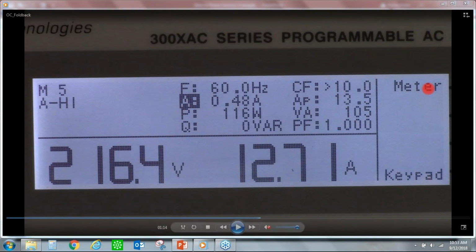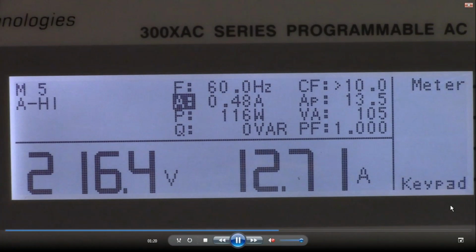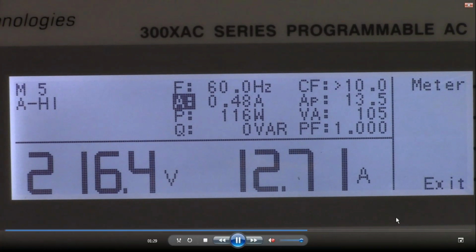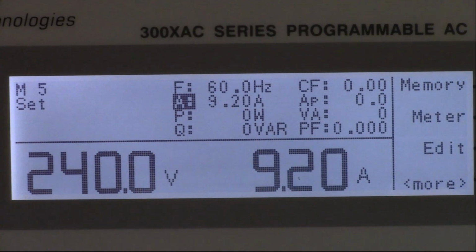But the feature that allows it to power up is called the OC fallback. What we are going to do here is quickly turn on the OC fallback feature. When we turn on the OC fallback feature, you will see that the voltage is going to sag. And when the voltage is sagging down, the current requirements are met, and the motor starts spinning, and the voltage will come back to an appropriate level once it goes into a steady state.